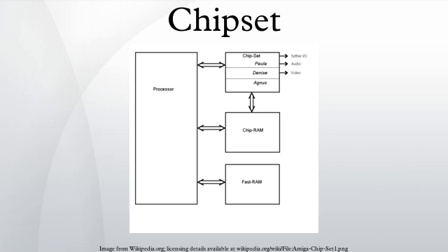Based on Intel Pentium-class microprocessors, the term chipset often refers to a specific pair of chips on the motherboard, the North Bridge and the South Bridge. The North Bridge links the CPU to very high-speed devices, especially RAM and graphics controllers, and the South Bridge connects to lower-speed peripheral buses. In many modern chipsets, the South Bridge contains some on-chip integrated peripherals, such as Ethernet, USB, and audio devices. The manufacturer of a chipset often is independent from the manufacturer of the motherboard.